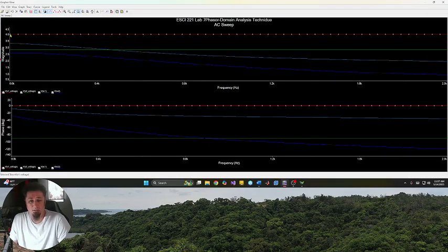We have our 4 volts at the input of voltage source 1, and the 2.828 right here, this green line. Then we have VA, which is decreasing through here, and VB, which is decreasing through there. Same thing with the phase in degrees. We have 0 degrees for voltage source 1, minus 90 degrees for voltage source 2, and we can see a decrease in degrees as we get further away.